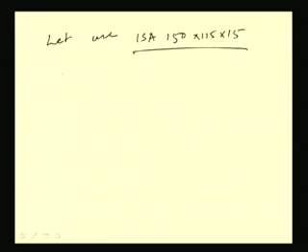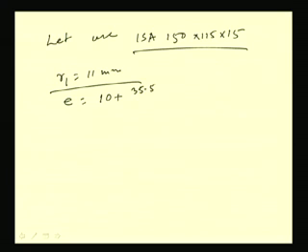Then from SP6 R1 can be found out, which is given as 11 millimeter. So eccentricity E is 10 plus B by 2, that means 30.56 by 2, minus thickness T which is 15 here, and R1 is 11. After calculating this we are getting 1.78 millimeter.